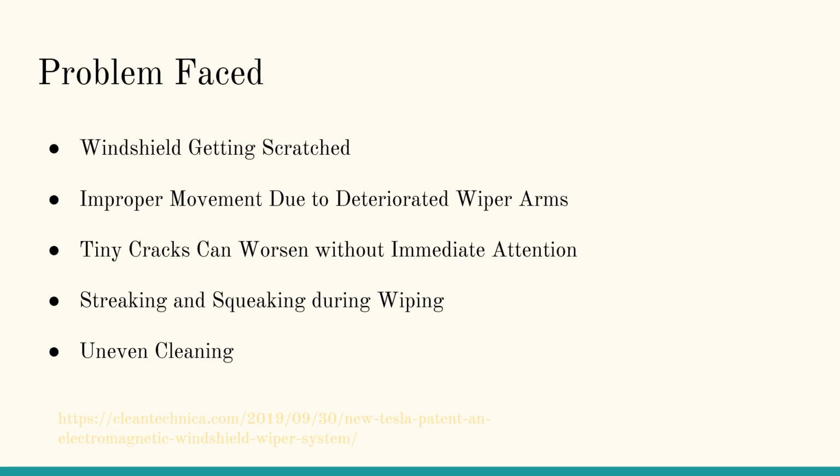If there are scratches already on your windshield, these damages will only deepen and aggravate until a point when windshield replacement becomes the only viable option. The last two problems faced are streaking and squeaking during wiping. The rough edges of faulty wipers in your car can cause excessive streaking, scraping and grinding, and other unusual sounds when your wipers are in use. They also cause uneven cleaning. If your wiper blades are not functioning correctly, they will not clean your windshield properly and will leave sections unattended.